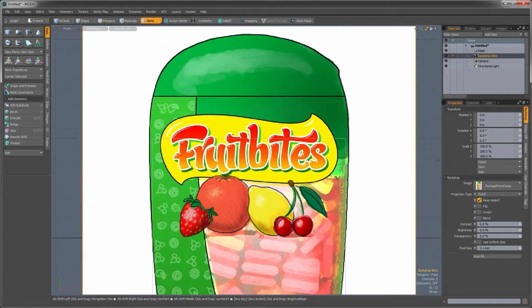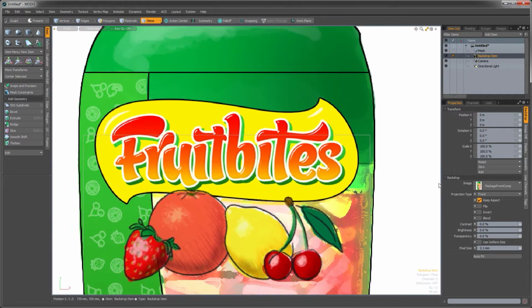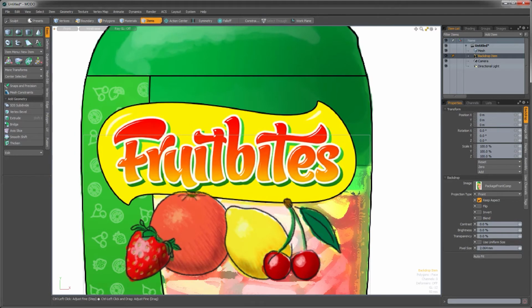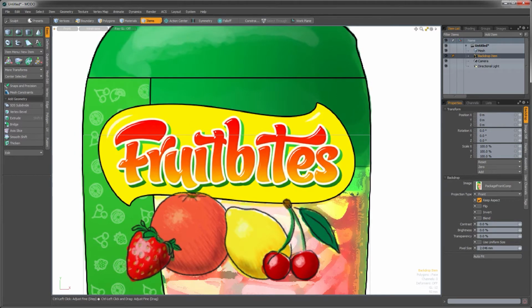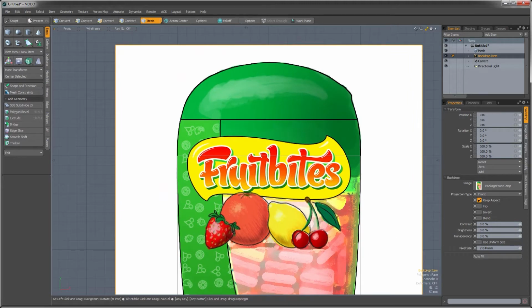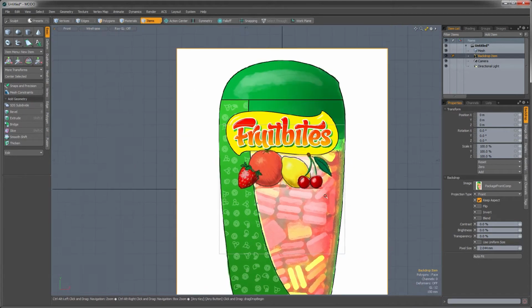We want these black lines to just sort of hug the outside of the cube size. If you hold down the control key and then move the little slider, you can actually get a finer little representation there. So I have mine at 2.044 millimeters for the pixel size. And that seems to get me the size that I want.